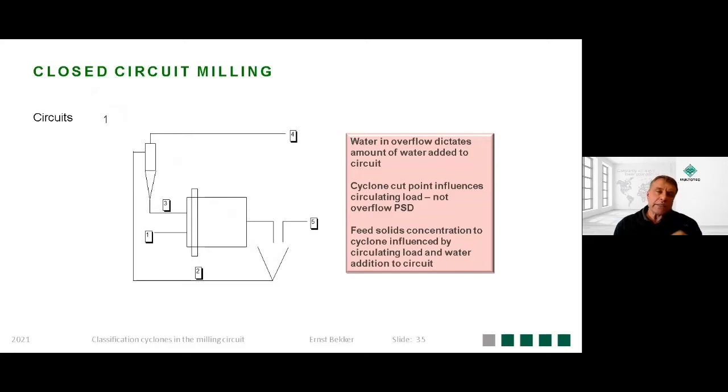And then the client says, my cyclone is not operating efficiently. But Mr. Client, there's too little water. There's so much solids going around. And then the question comes in, but why are those circulating loads so high? Something else has changed in the circuit.